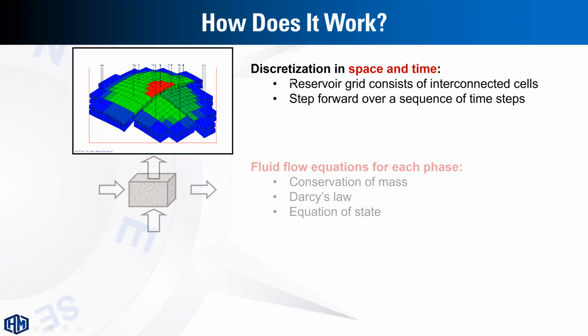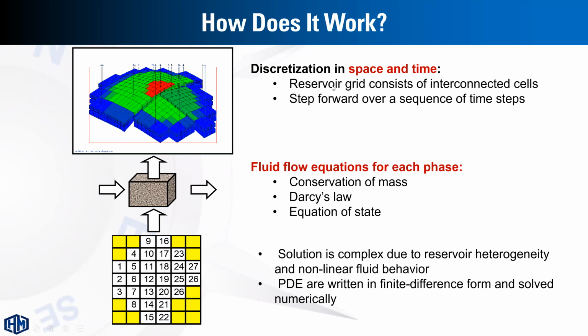So simply we have discretization or subdivision in space and time to subdivide the model into 3D grids, and in time we have a specific time step. We solve simulation equations, which are nonlinear equations due to the reservoir complexity and nonlinear fluid behavior.